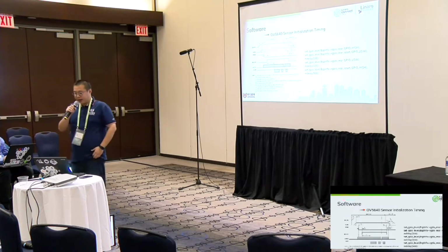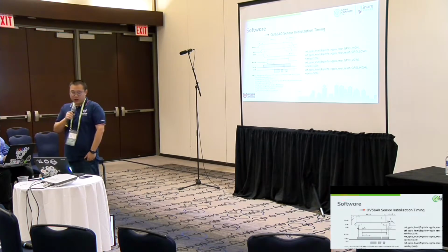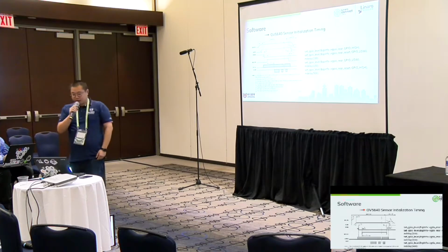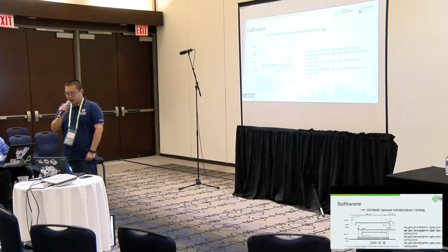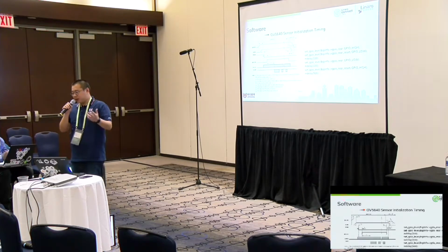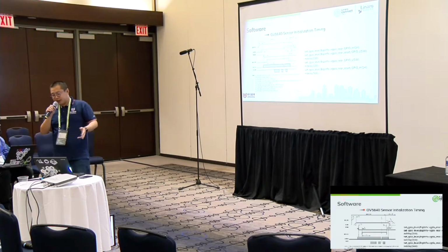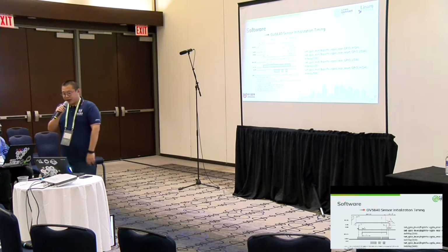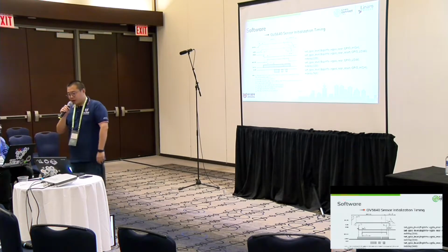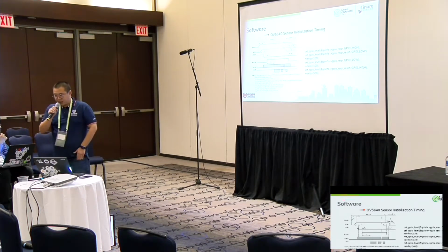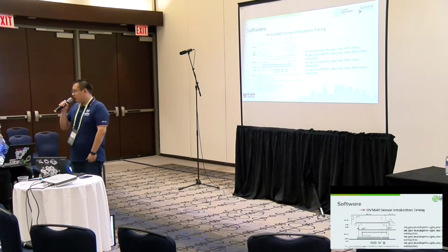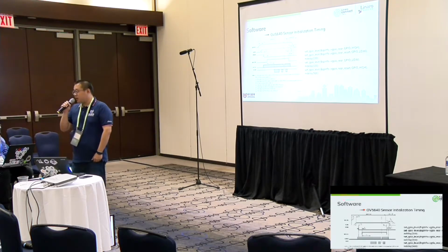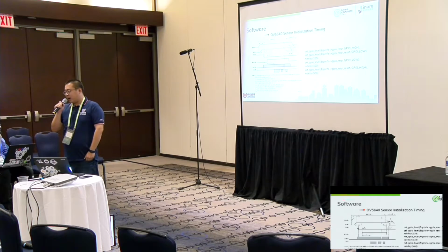So here is the OV sensor initialization timing. The picture on the left is a screenshot from the data sheet of the OV sensor, and we have solved the initialization timing of DVDD, DOVDD, AVDD by hardware.